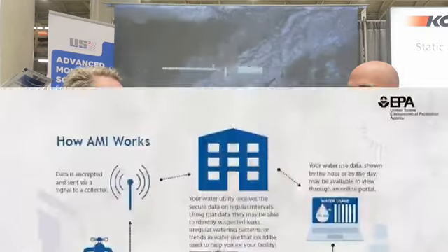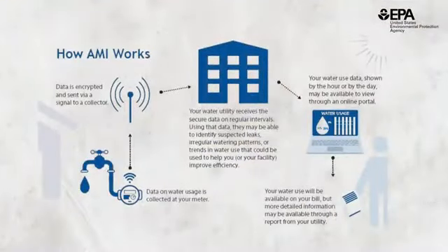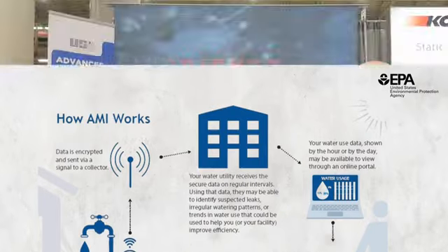And then of course, we're not believers in putting sensors in for years to identify where the problems are. We think it takes weeks, maybe a couple months. Really, we were talking about the dry weather data, wet weather data, and then your AMI data. The AMI data, by the way, really pinpoints where the problem is. It's on every single home. It's a water meter on every home. So the granularity of that information is a game changer in how to identify problems.